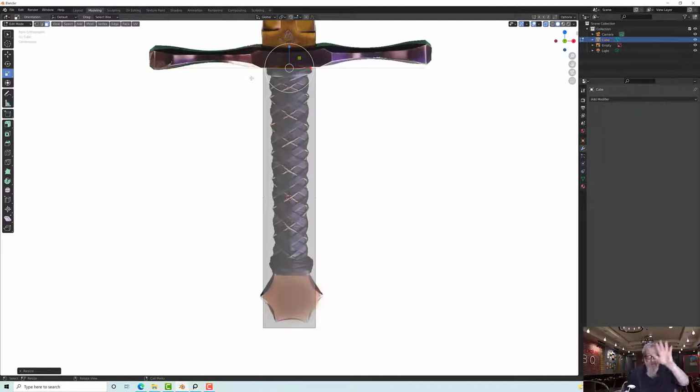And once you've got your width and height, or width and depth, set, we're going to extrude it up to form a box. So over here we have various operation menus, and at the top is extrude, and I'm going to click extrude along normals because it's the one I always use, even if I don't need to sometimes, because it will extrude it along the normal of the polygon. The normal is the direction that polygon is facing, at 90 degrees to itself.